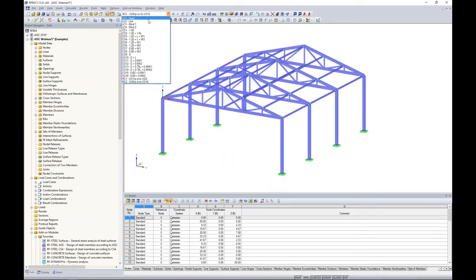Now, utilizing this drop-down box, we want to make sure that we have the correct load case available here before we move on to applying loads to the member. Dead load, we're going to assume that just self-weight is fine for today's example. I'm not going to add on any other loads. So we'll scroll then to live load.